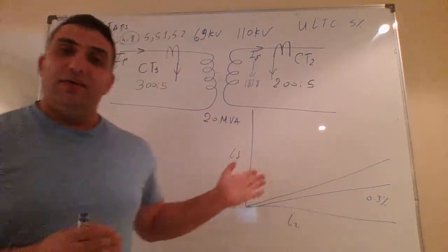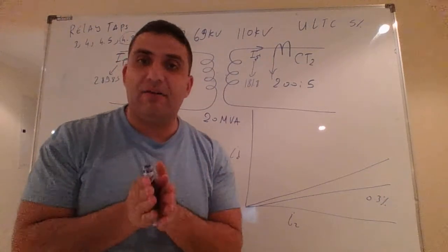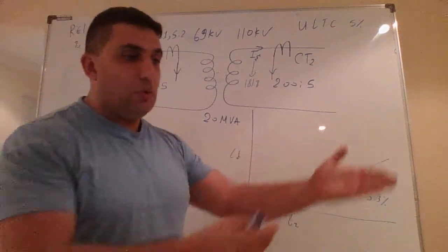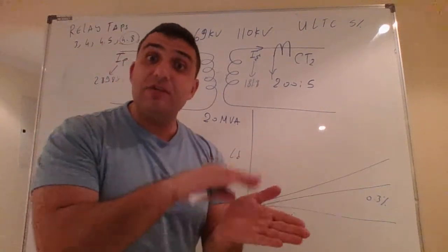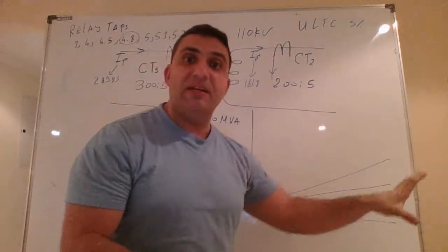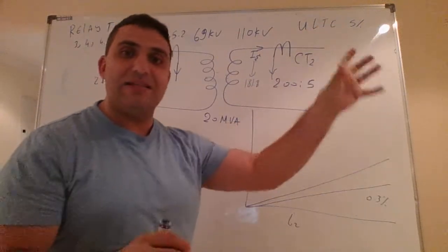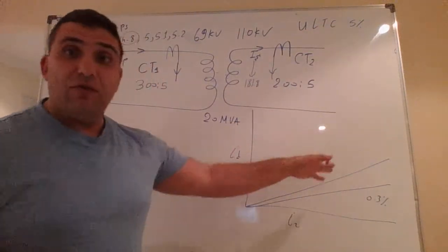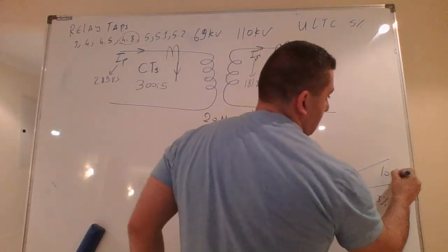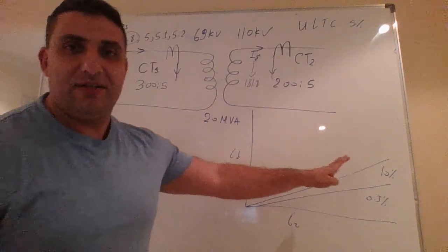Now, two options. Either we will have the input data to calculate the CT error as we've done in the previous chapters, or we will go into the data sheet as we did in the previous homework. We go to a data sheet and find a CT with a nominated error, and we say this is the CT type that we're using, this brand, and this is the error. For the sake of this example, I want to say it is 10%.